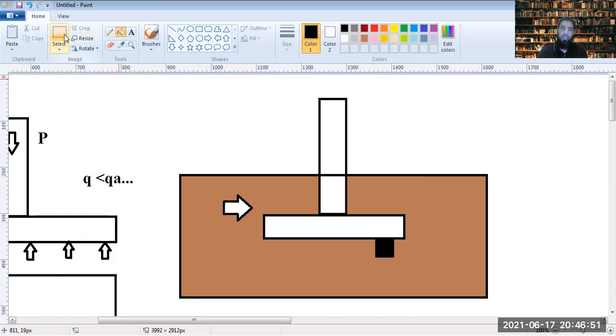To prevent the overturning of this system, of this isolated footing, what we usually do is keep a balance between this side and this side, the right side and the left side. Keeping a balance is a good thing, because for footings, like in a retaining wall, we have a heel and we have a toe, just like in the foot. If the heel and the toe are not balanced out, the system could actually topple over about this footing. So there could be a toppling action about this footing.